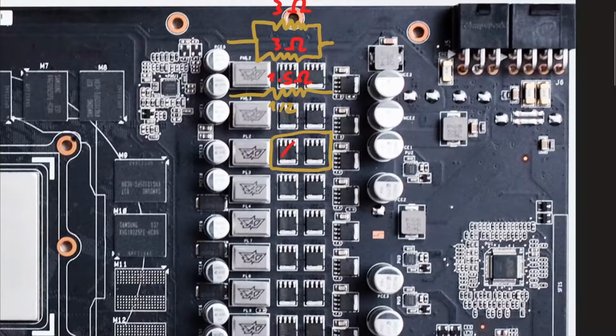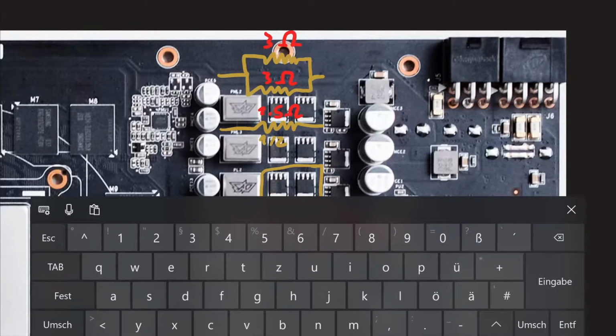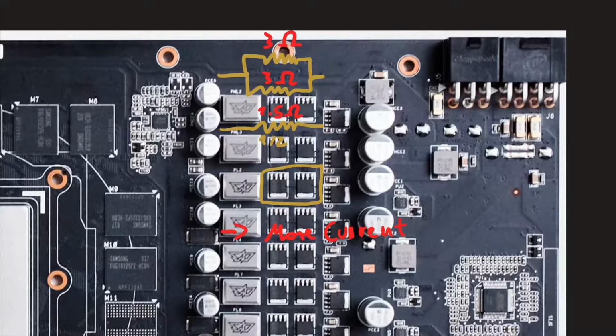So yeah, then there's basically two things you get from putting two low-side MOSFETs on a VRM. You get more current, because MOSFETs can only handle that much current, like they are spec'd for a certain current number, and if they go over that, they will just blow up.